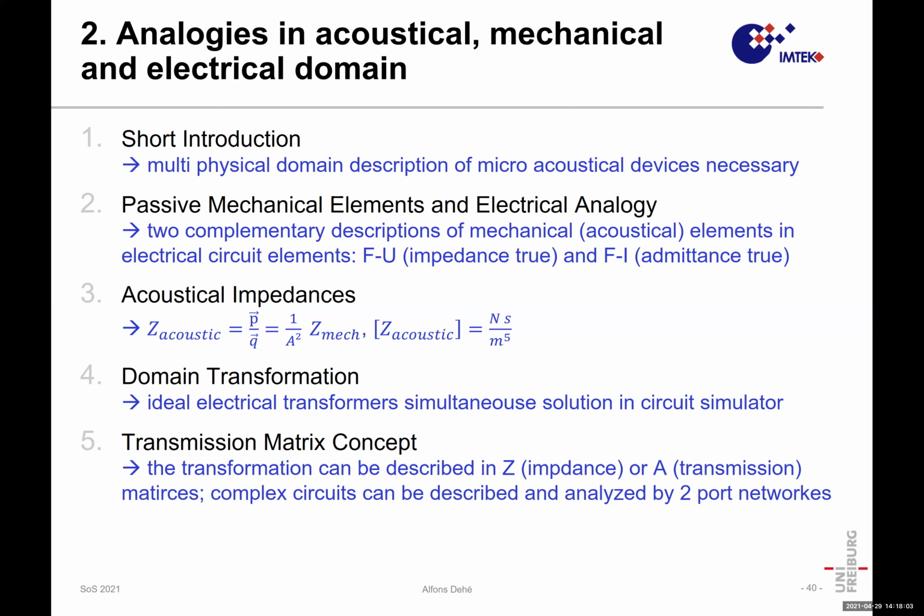Yeah, with ideal electrical transformers, we can even bridge between the different domains and do a joint simulation in a circuit simulator. And alternatively, we can solve those networks by transmission matrix concepts in terms of two-port networks. Yes, this is what we could share today.